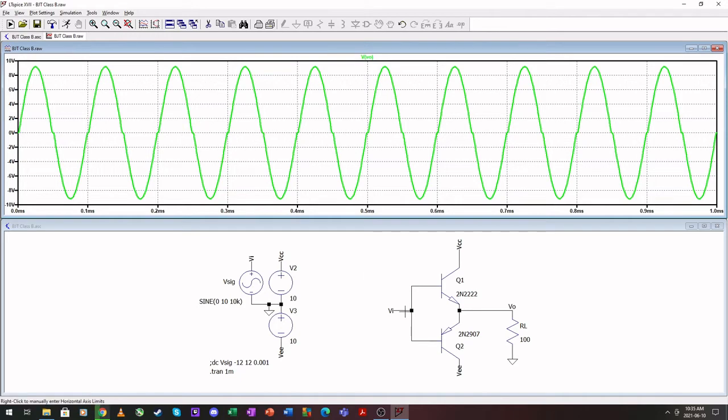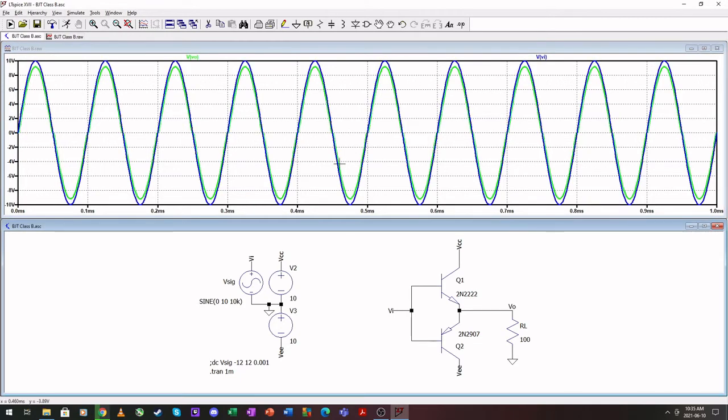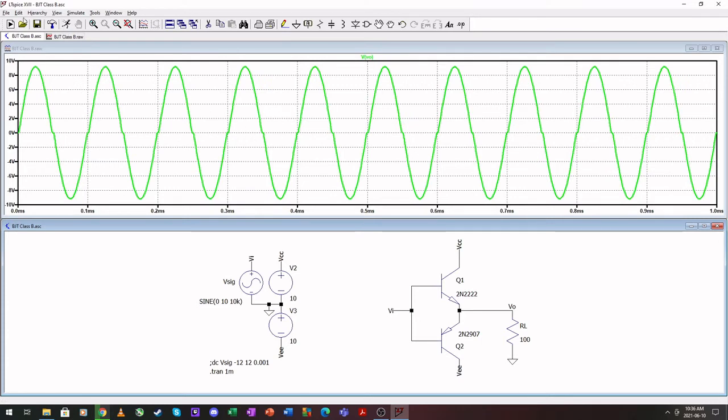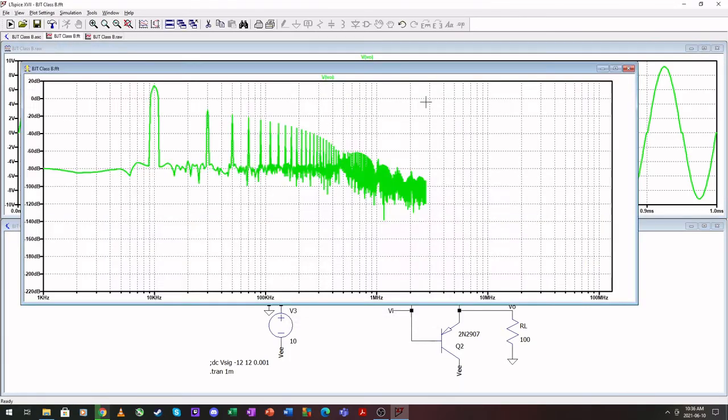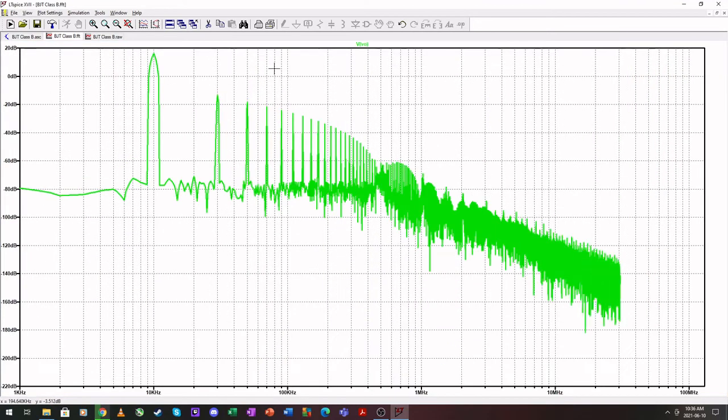Versus our input, it becomes a little bit smaller than our input originally was, 5.7, 0.5. So we have a bit of a decrease in output voltage due to that. And just to make the distortion clear, if we do FFT, here's our original signal, and we will have these harmonics starting to exist on our output due to that dead part.